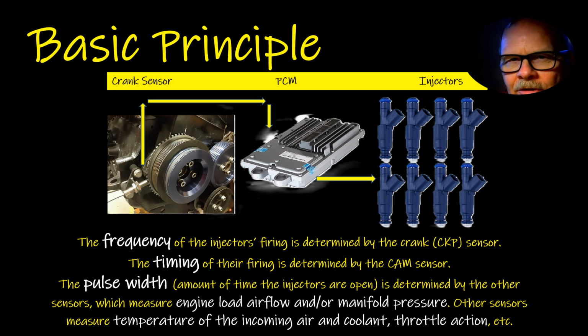I could turn that distributor, set the crankshaft on 24 degrees after top dead center. You have to do some measuring to do that. Then you turn that distributor, watching an LED that you've got connected to the cam sensor input to the engine controller, and you turn it so that that switch is happening at 24 degrees after, and everything works just like it's supposed to.